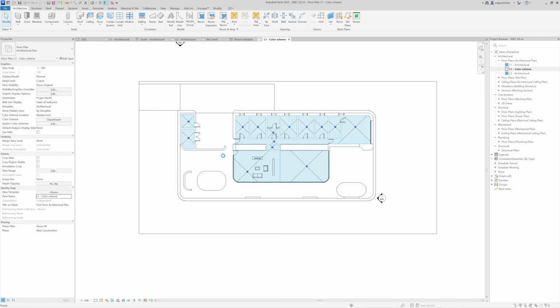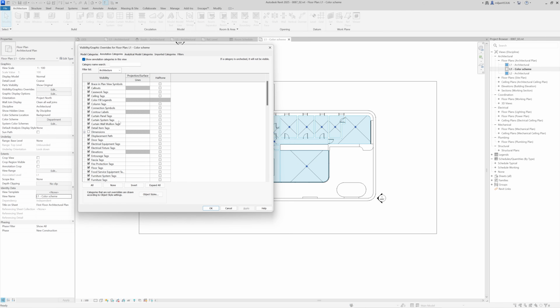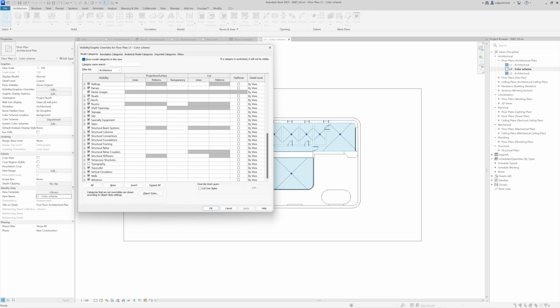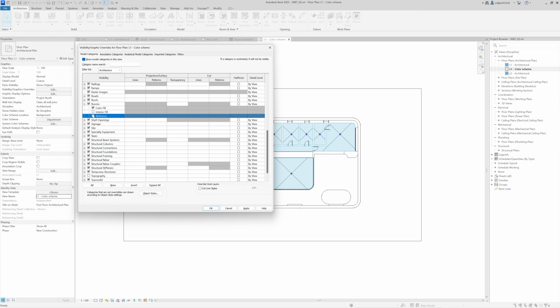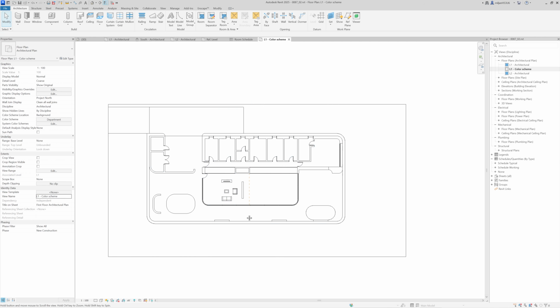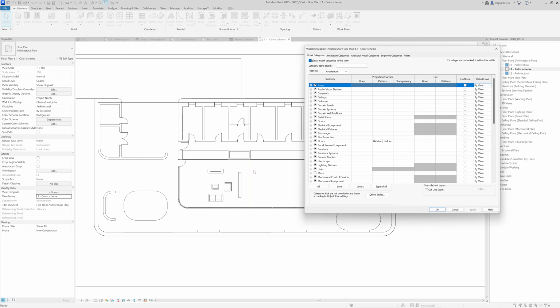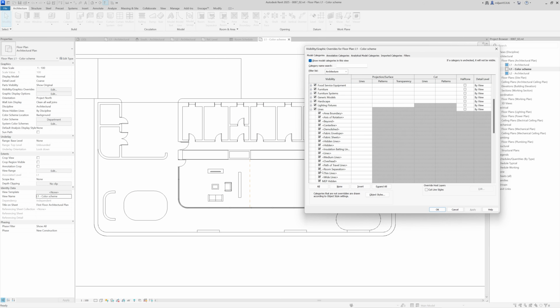And we also don't need to see elevations here in this view, and I'm going to turn them off. And by the way, also in this view, for the model categories, for the rooms, we don't need those interior fill and the reference. And also you see that we have visible this room separation line. So just go here to the lines and turn off room separation.